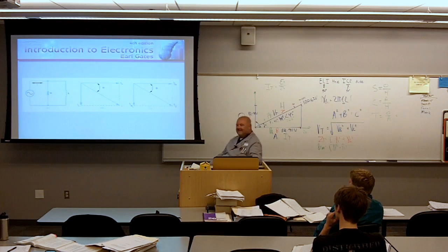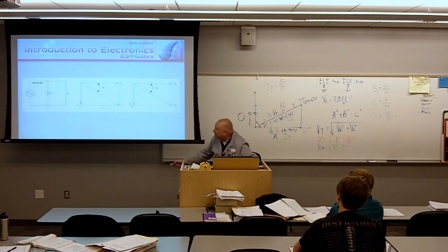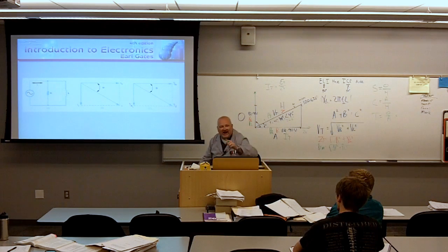Adjacent. Which side is my inductor, current through the inductor? Opposite. My hypotenuse is going to be the total current through the circuit, the combination of this and this. Classic example on a professional exam.